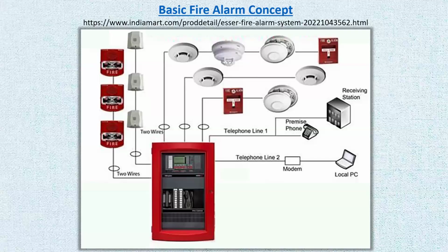Now, if it comes to ceiling space where there's lots of insulation and lots of dust and so on, of course, the dry powder extinguishers will put out the fire for a little bit, and the fire can reignite. So wet fire extinguishers have to be applied, for example, filled with water. Okay.